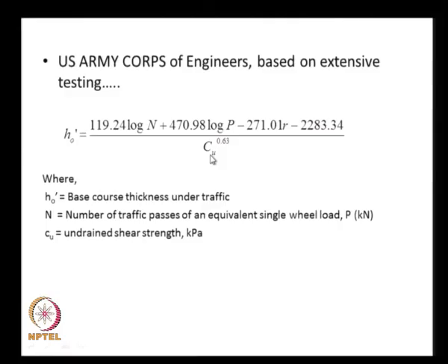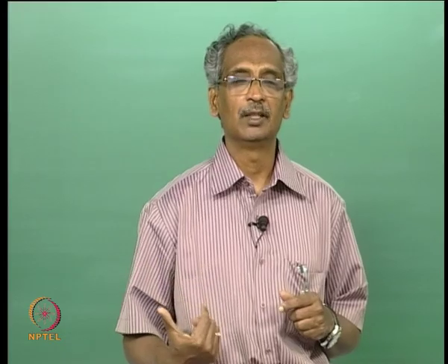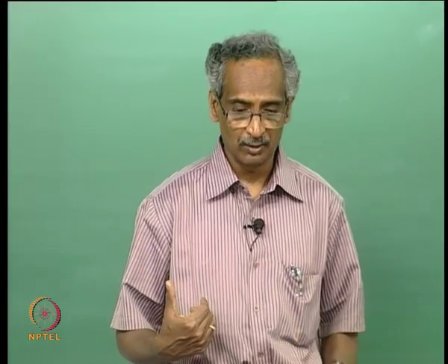Either Cu or CBR, both are linearly related to each other. The Cu is approximately 30 times the CBR in kilopascal units,